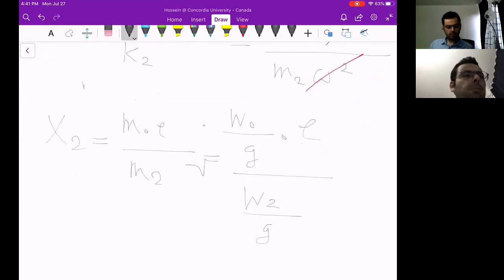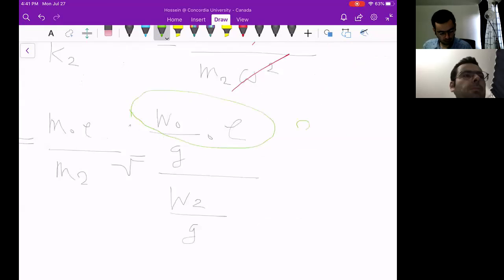If you take a look at the question given, the unbalanced rotating mass is given in terms of 2 pound inch. So you have to draw the conclusion that the multiplication of weight and eccentricity is given to you.